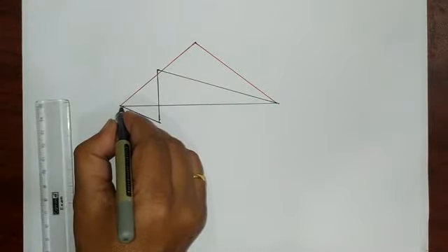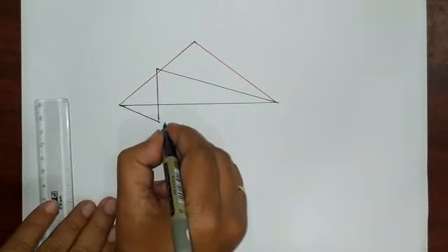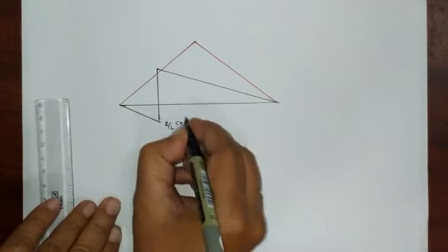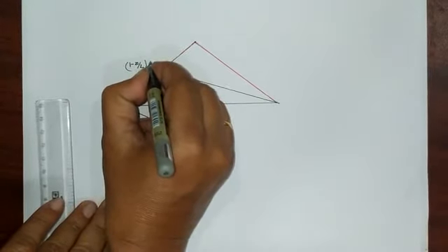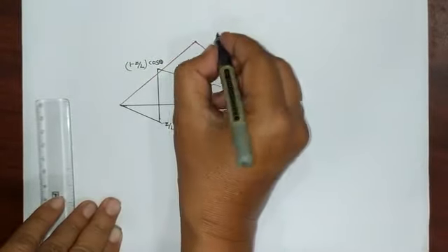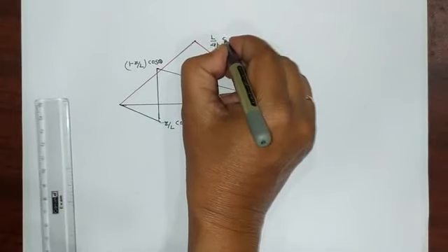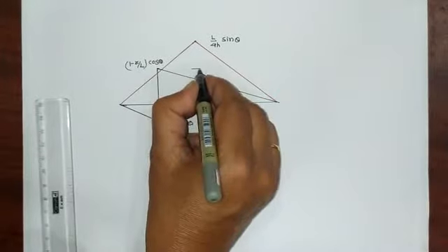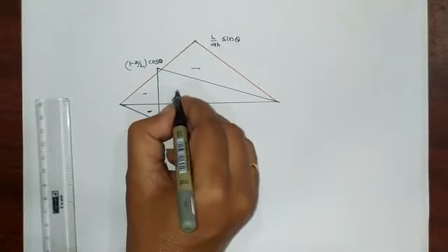So we got the combined diagram for V cos theta minus H sin theta. The first diagram in black color is for V cos theta, that is Z by L into cos theta, and 1 minus Z by L into cos theta, and this alternate is L by 4H into sin theta. We know this part is minus.